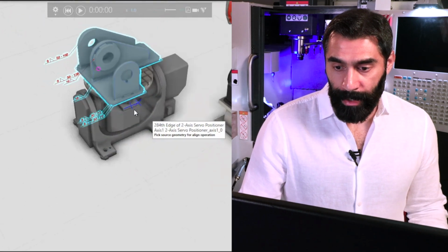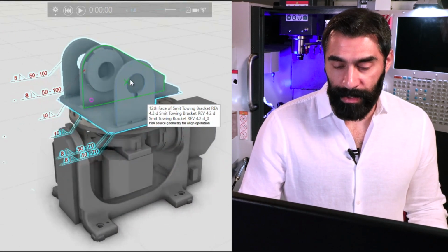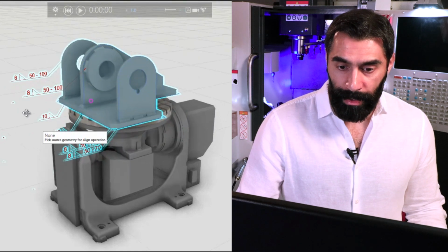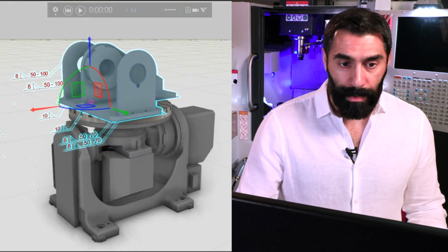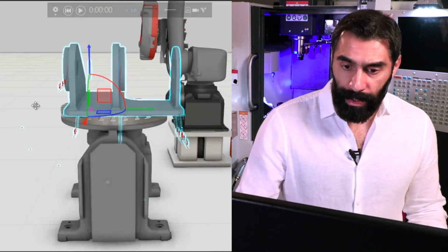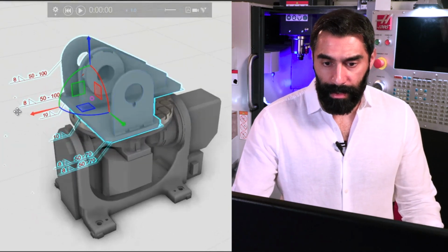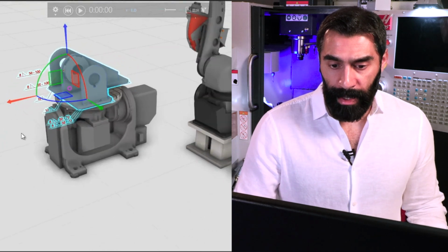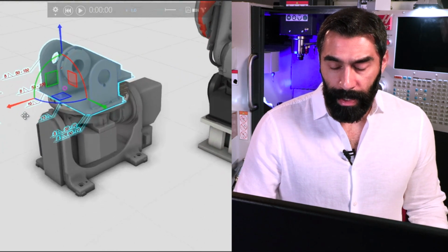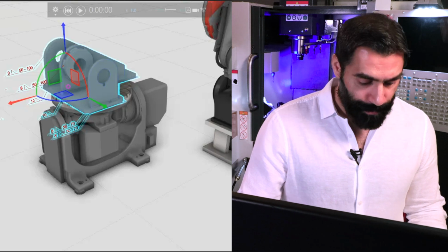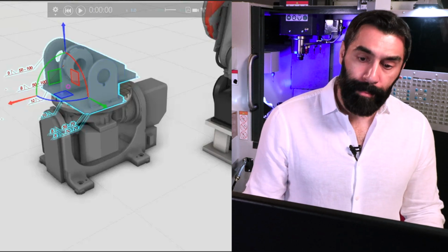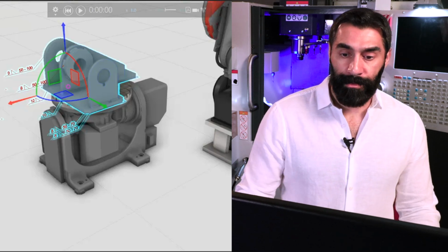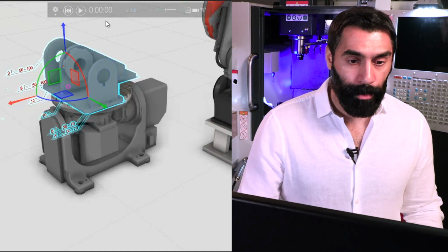You can see that by opening up the step file. In this case, we saved it out as a STEP 242 file. I can also see my model-based definition, the weld callouts. In this particular case, these weld callouts I'm not going to use, so I'm going to delete them. And I'm going to import the weld information from the QIF to generate the robot program.